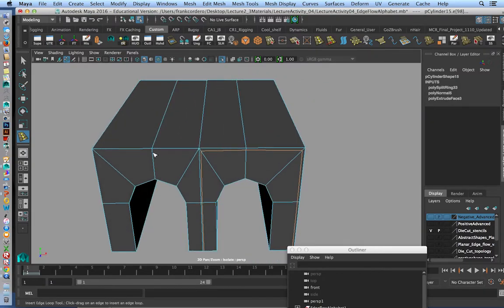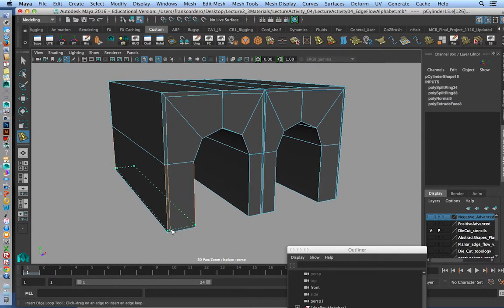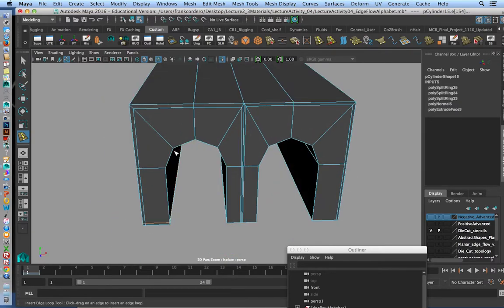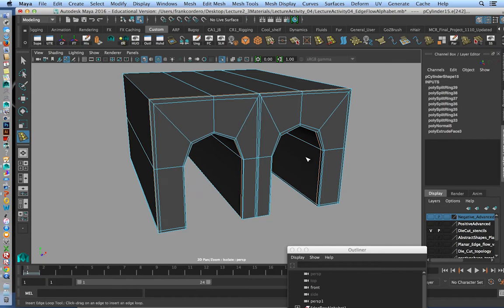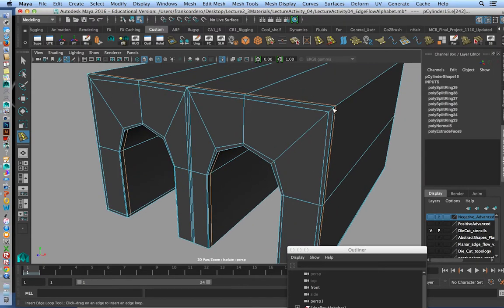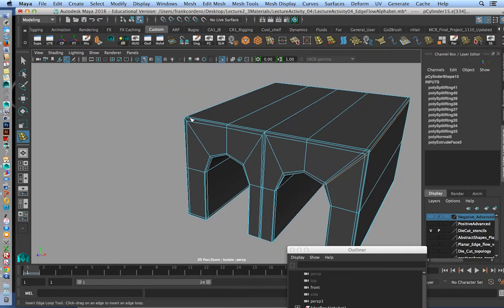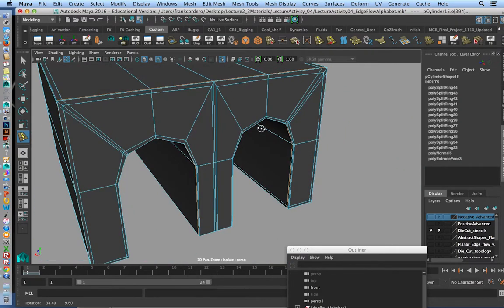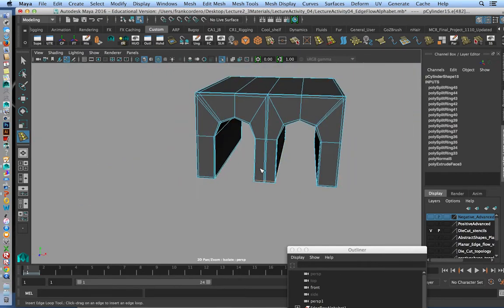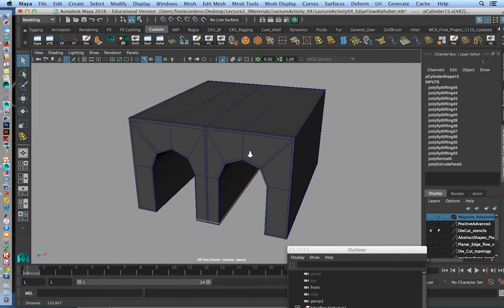Let me show you what I'm talking about. I'll go ahead and add the holding edges to the shape. Now it's already redirecting. If you notice, the traffic is kind of shooting down. Now if I hit the 3 key, you see I still need some in the corner. So now I also have to make sure I add holding edges to keep the corner up. When we do that, we're also going to create a situation that affects our shapes elsewhere.